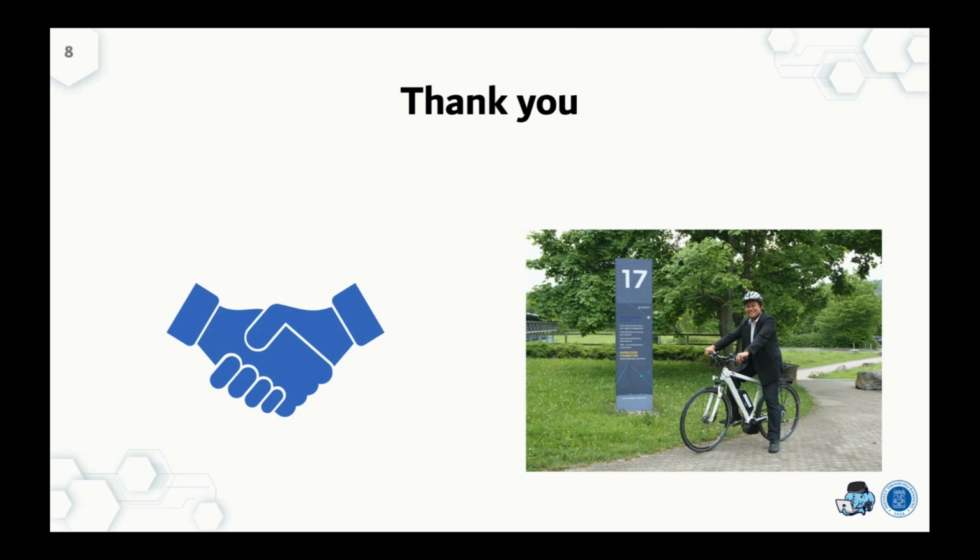I hope this information, together with the examples, gives you an insight into how we can measure the process. After we have defined that the process is in control, we should use both the capability ratio and the capability index to measure whether our process is capable of meeting our requirement.